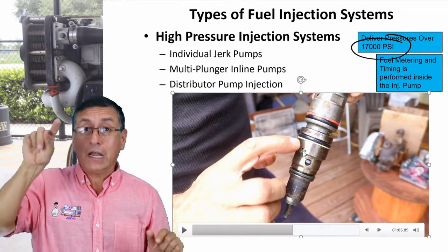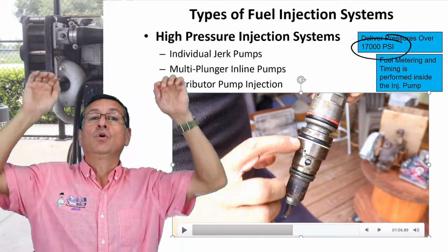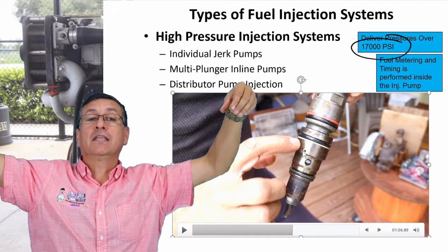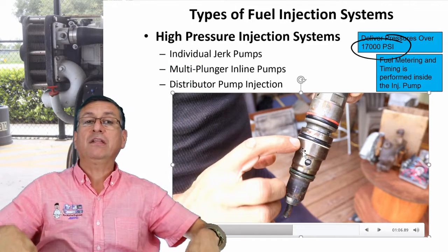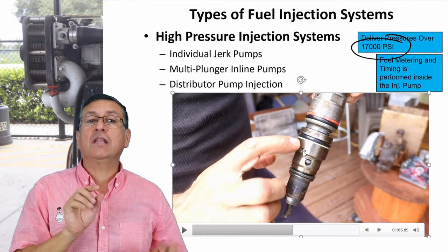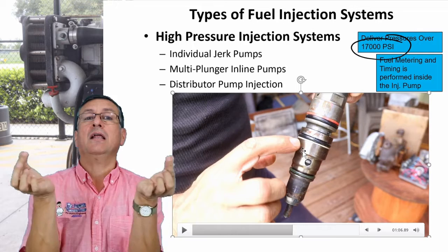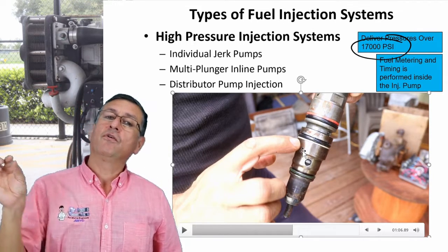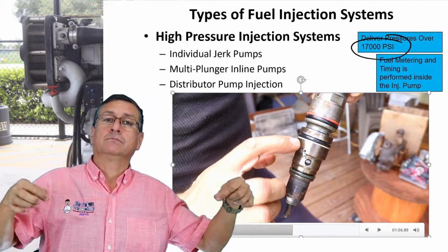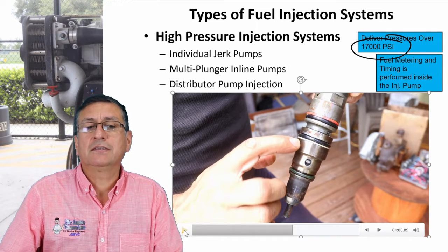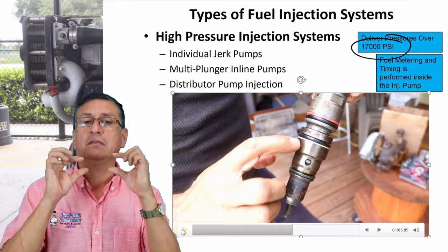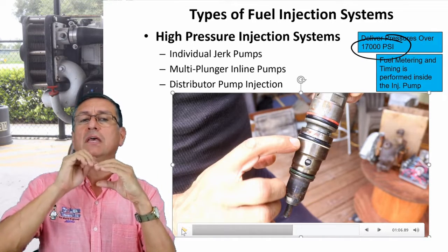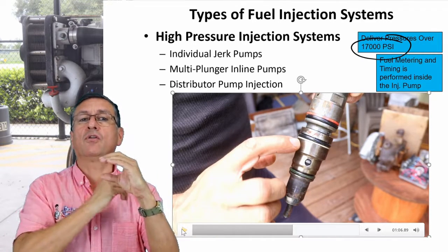You have oil to lubricate the rocker arms, and after that the oil drops by gravity into the oil pan. And additionally, you have cavities internally for the fuel, for intake and for return. Alright, my friend, this is the return, and it is separated with O-rings. Internally, the cavities have O-rings in order to avoid the fuel migrating into other cavities.